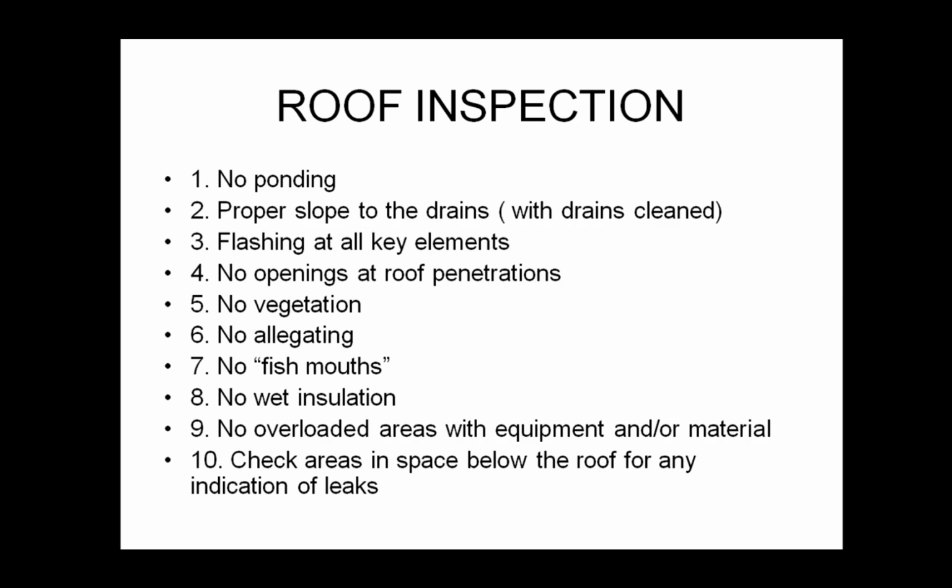So you likely don't have the proper slope if you have ponding somewhere. You want to make sure that you have flashing at all the key elements to protect against leakage behind that flashing, or seeping through those tiny openings. You want to make sure that all the penetrations are properly sealed. We saw how that can be done on one of the slides before: a number of layers of material leading up to the mouth of where the penetration is, and just making sure that those are nice and sealed.